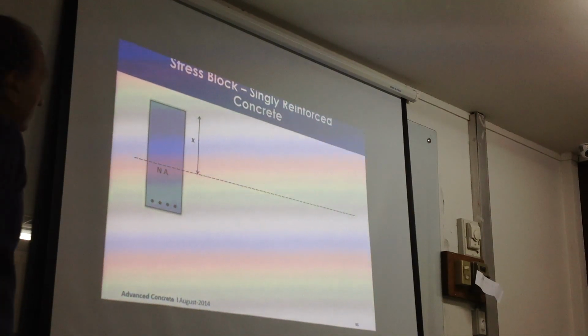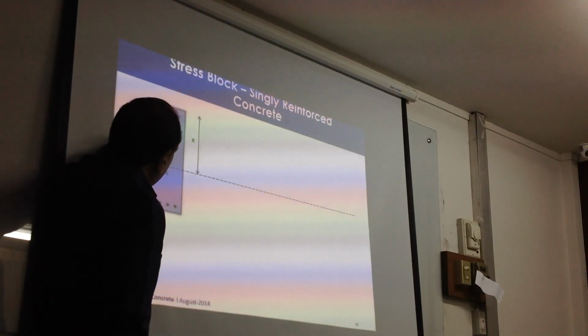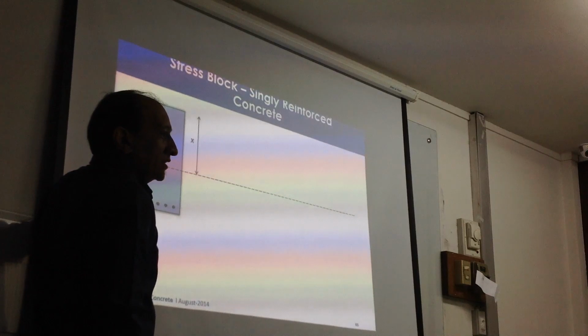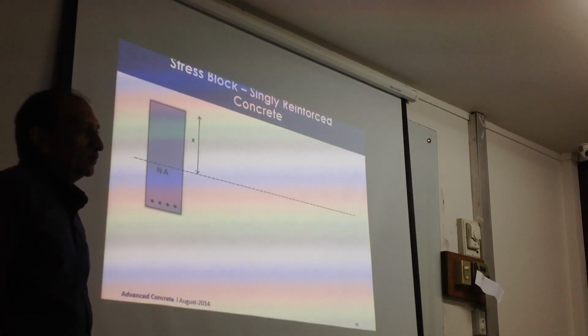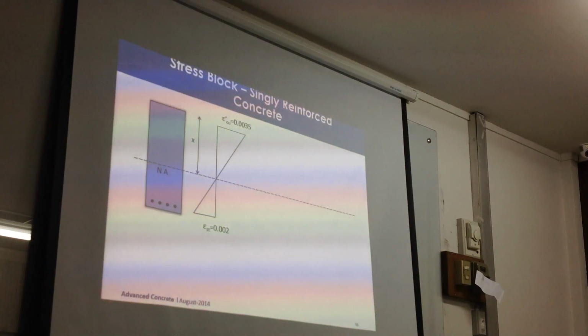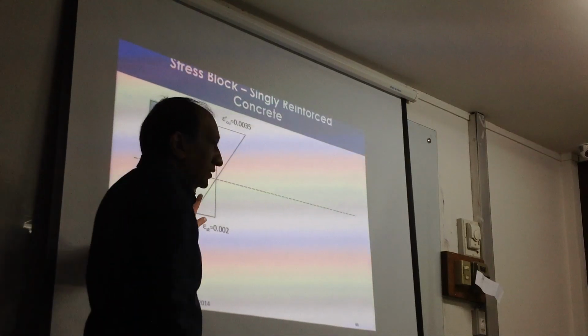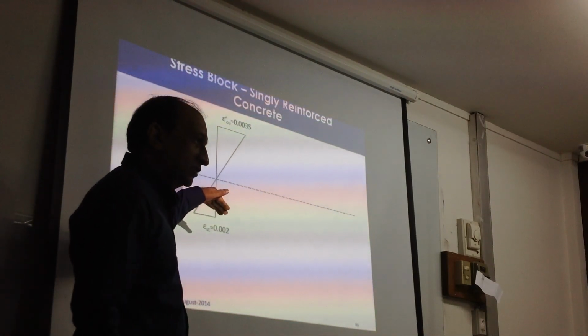So now we are dealing with a simplified system. Duplexes, cross-section, bars only on one side, no compression bars, very simple. First, the singly reinforced beam that you people have all studied. We can draw the strain diagram like this. This information will help you to do the assignment because this tells you how these things work.